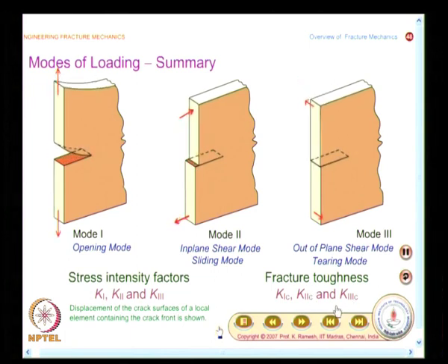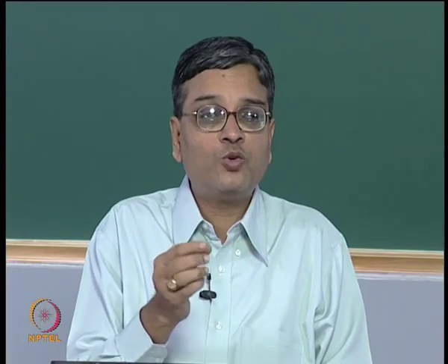And I had already noted, see, in the case of simple strength of materials, what did you do? When you had combined loading, you invented the concept of principal stresses and you utilized the result from a simple tension test of the yield strength, and you find out how the failure will occur in combined loading. You do only one test.